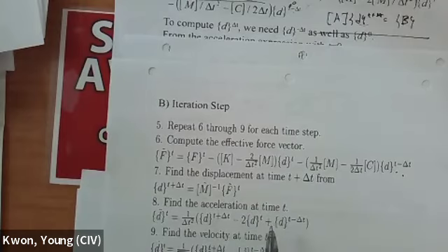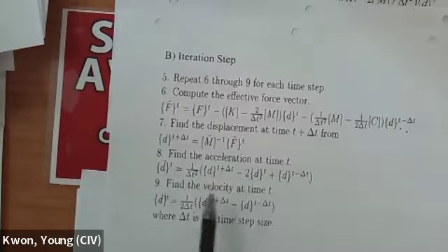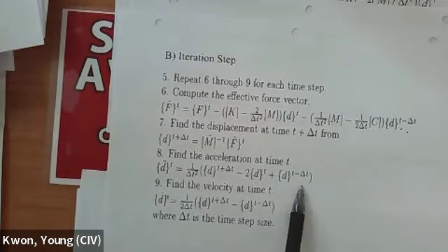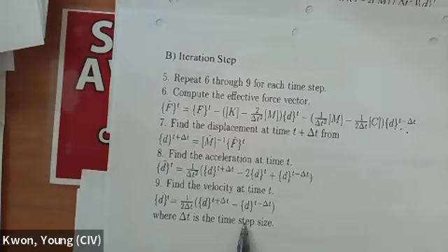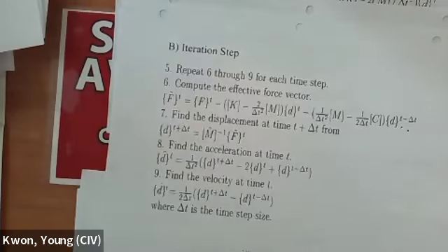And then once you have the new displacement solution, taking the standard acceleration and velocity formulations, you can calculate the acceleration and velocity at t plus delta t. So you can continue this over and over. Got it? But this technique, as I said, needs the solution at two consecutive previous times, t and t minus delta t. That's why we need the fictitious solution to start with.